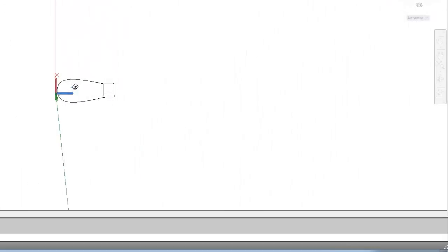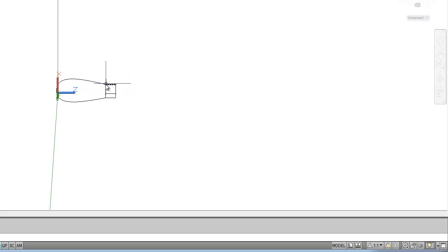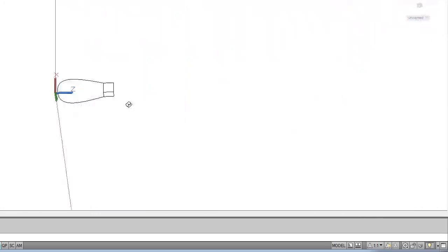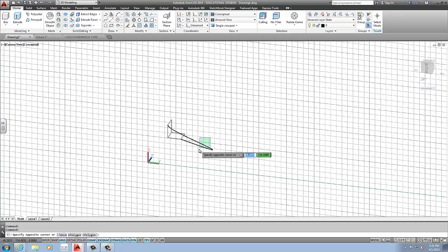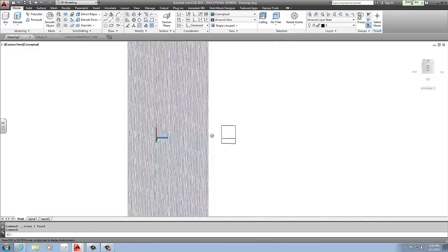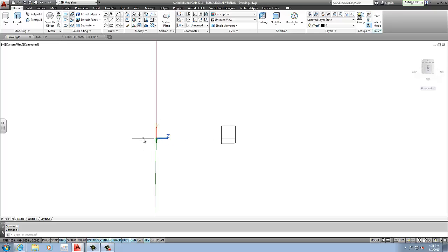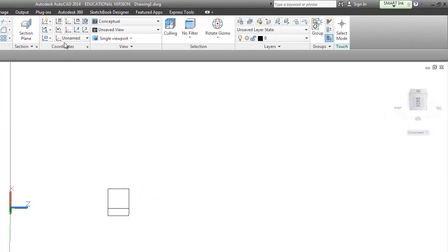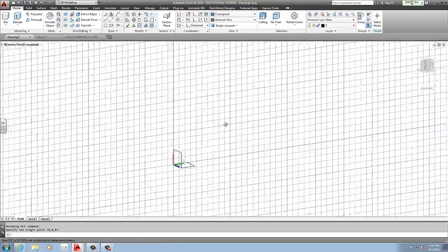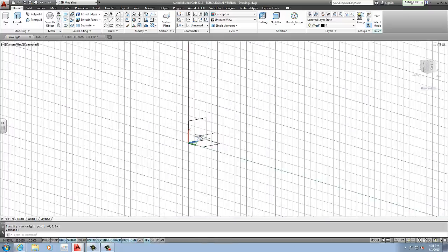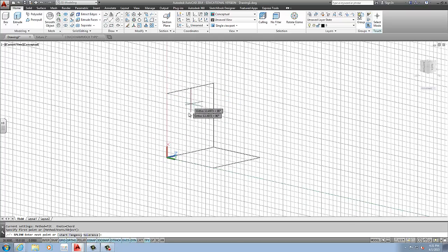As you can see, that plane is my X and Y. Now that I have this drawn somewhere on a Z axis, it snapped onto those endpoints, and that's what it created. So when you see errors, that's what happens: it snaps onto something that is no longer on the X and Y plane. To fix that, there are a few different ways. You can move the object so that its edge is aligned with the X and Y plane. The other option, which is probably simpler, is to define the origin, so you place it on the part or a surface. Now that plane is exactly on that drawing that I created. Now I can go back to the spline once more and create that lovely spline.